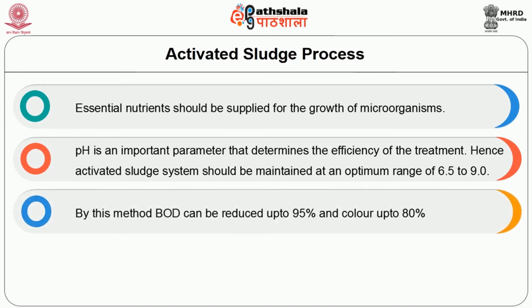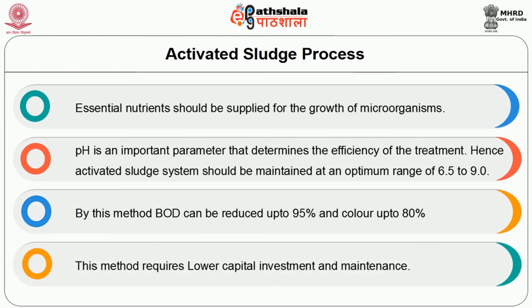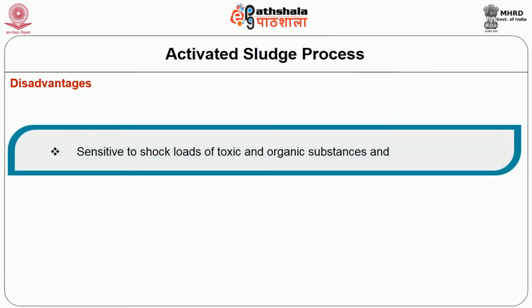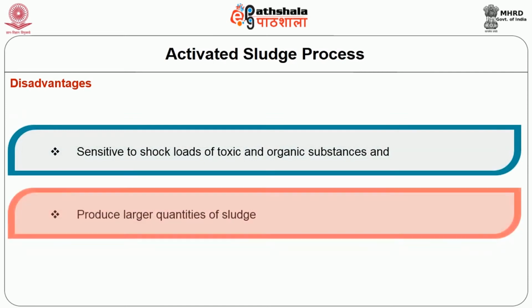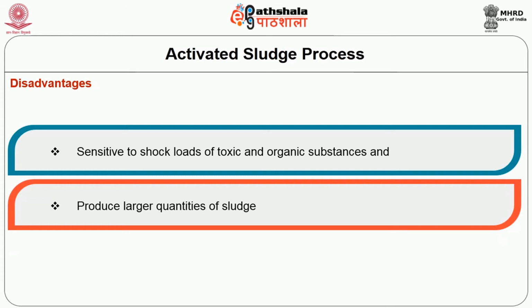By this method, BOD can be reduced up to 95% and color up to 80%. This method requires lower capital investment and maintenance. The disadvantages of this technique is that they are sensitive to shock loads of toxic and organic substances and they produce larger quantities of sludge.